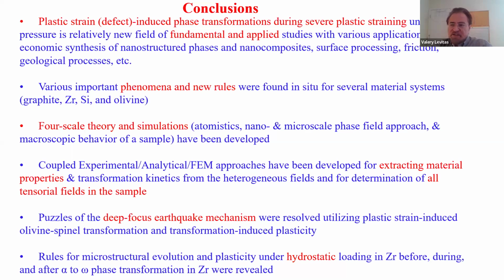Even what was measured, it's not our work, but by people who do high pressure torsion with ceramic or metallic anvils for large samples, with a diameter of 1 centimeter, in contrast to our 0.5 millimeter, the increase in temperature is like 10 degrees, maybe 20 degrees. So in our case, it's completely negligible. It's small even at 100 rotations per minute. And what will happen at higher rotation rates, we plan to go to 4,000 rotations per minute, I don't know, but it will not be drastic. It will be maybe within tens of degrees.